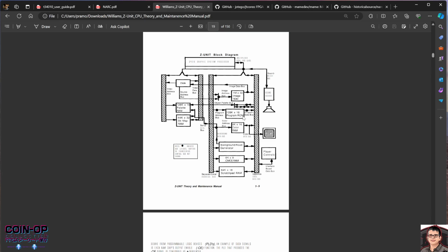The FPGA core, though, is a translation of analog to digital logic, right? So you're not going to be able to copy this exactly. You can get the high level architecture in there, but ultimately, due to the way the FPGA dev board is designed, you're not going to be implementing all of this exactly as you see it. You're going to try to take what's here and replicate it using digital logic, and using different sorts of components to achieve memory rates or different techniques that you might use with FPGA resources to replicate it.